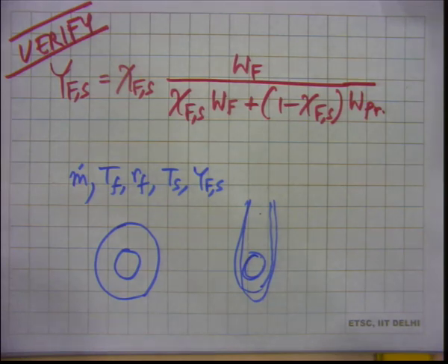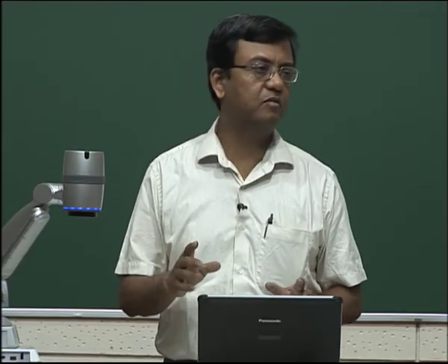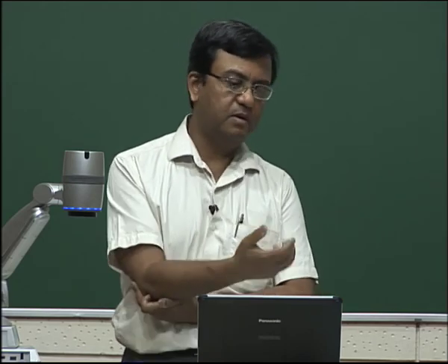And to understand liquid fuel combustion better, people have done experiments where there is less gravity. You can do that by making an instrumented box and having a liquid droplet suspended there somehow, and then the droplet can burn, and you can drop the box from the top of a tower. Okay, this sounds simplistic, but that is what is actually done at space agencies, for example at NASA or at the Japanese Space Agency. If you do that, then you get the spherical flame which we are talking about. These are called free fall experiments, and you get a very short duration of time while the box is falling with a burning droplet in it. The amount of time that you get in low gravity is roughly the time it takes to fall from that height to the ground level. So that is maybe 1 or 2 seconds.